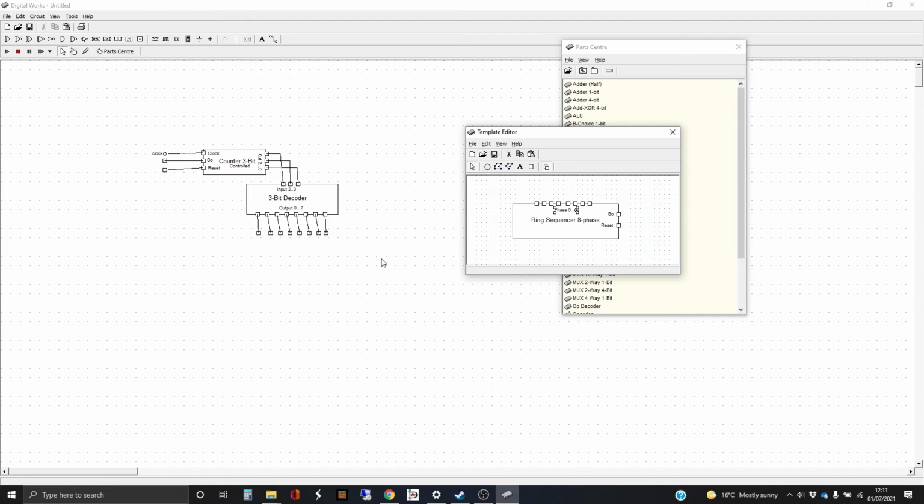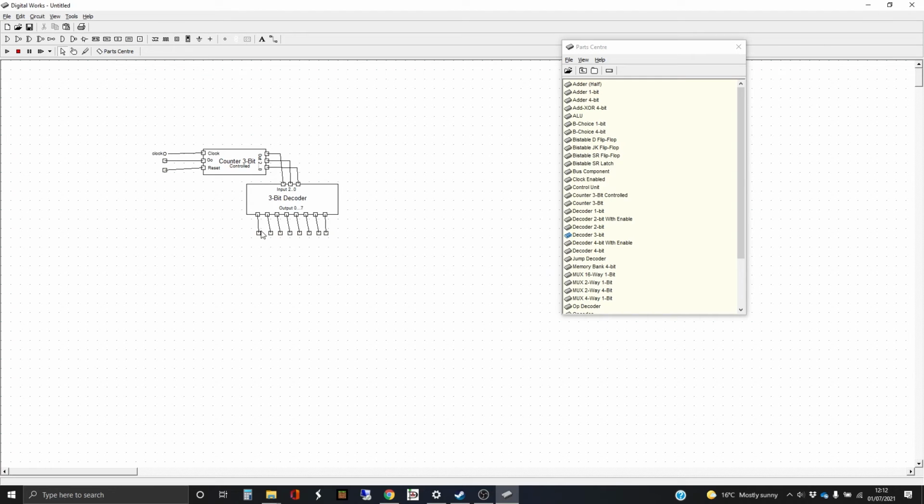When you're doing a binary number and you're doing it in pins and it's horizontal, then you tend to have that in the order in which you would write it as a number, which is with the most significant bit at the left-hand end and the least significant bit at the right-hand end. But when you've got discrete lines, you tend to do what conceptually is sort of the opposite, which is you have the first one, you have 0 at the left-hand end and count up to 7 or however many you're going to at the right-hand end, it's just conventions that work with the way we read English from left to right. So let's do the pin connecting up thing.